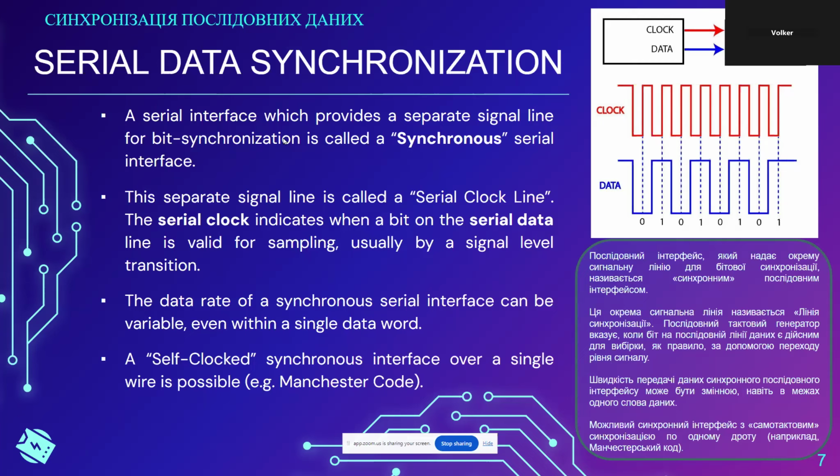The big advantage of the synchronous serial interface is that the speed is not really important. The receiving device will accept a bit when it sees the rising or falling edge of the clock signal. That's it. It doesn't care how much time has passed in between.